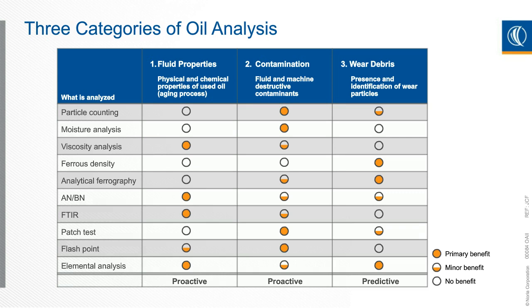So looking at the lubricant or other foreign substances that can become present in the oil, which indicate not only that the machine is already in an early sign of failure, but instead indicate the machine is currently in a state that will lead to a failure. Again, this is extremely important because if the root cause of a potential failure is observed before the machine itself is influenced by it, then it can be corrected proactively, leaving the machine without, potentially, any permanent degradative consequences.